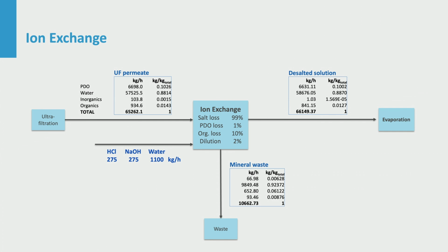After cation exchange, anion exchange is done in an analogous way, but using a column with an anion exchange resin in the OH- form and with sodium hydroxide solution for regeneration. Designing all these steps involves a lot of choices, and therefore only an approximate overall mass balance is shown here.